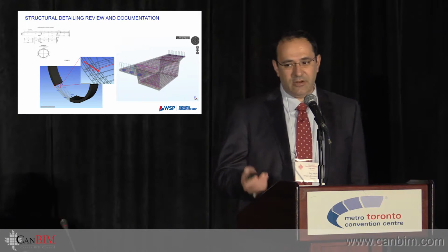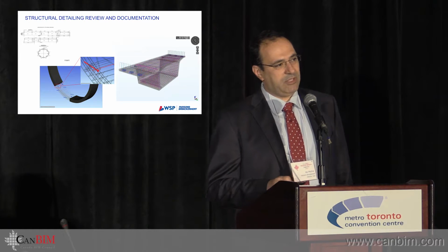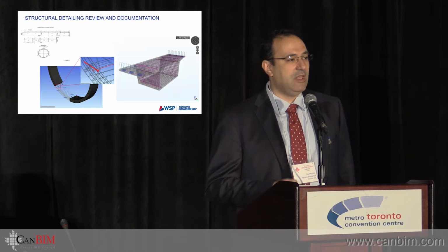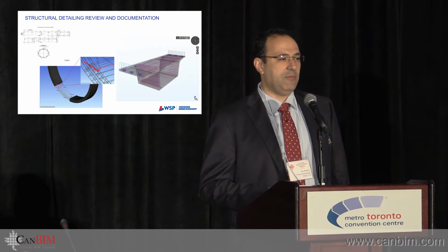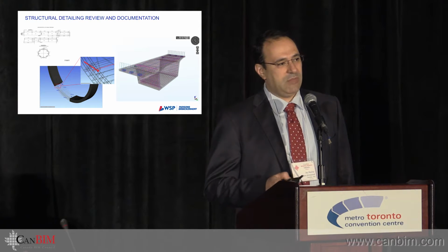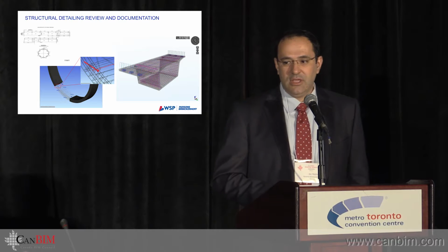In this case, it's a tunnel liner. We wanted to make sure that the rebar is not going to conflict with the dowels that connect the liners, and then also a bridge pier segment to generate all the rebar from the BIM model, because that would save the contractors money, and it's a much more efficient process in line with lean construction.